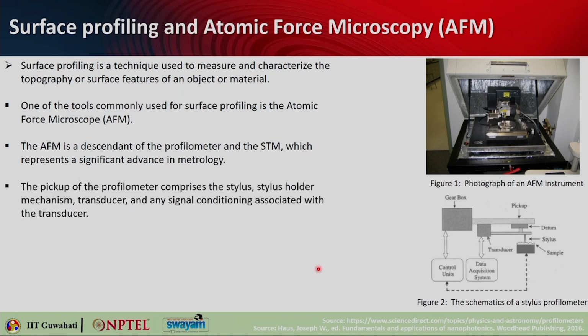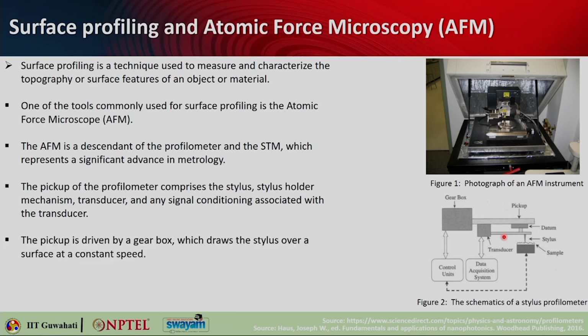Here you can see that there is a stylus that picks up the details from the sample. This part of the profilometer is called the pickup. The pickup comprises a stylus, a stylus holder mechanism, a transducer, and any signal conditioning circuit that is attached to the transducer.